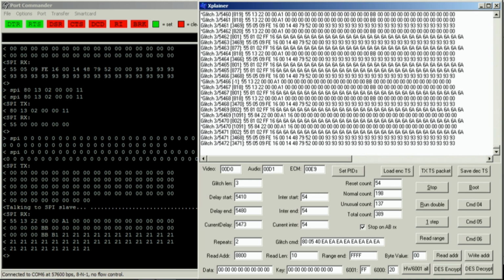There are specific addresses within RAM that can't be read, or the chip will lock up. These are clever traps put in as a safety measure. The 7-byte, 56-bit keys stored in RAM straddle these dead addresses. So any potential exploit that could cause a linear dump of memory will be stopped before you can even read a complete key. When the chip is reset, I have to glitch in again because my code payload exists only in RAM and there really is no way to hook in any kind of permanent backdoor.